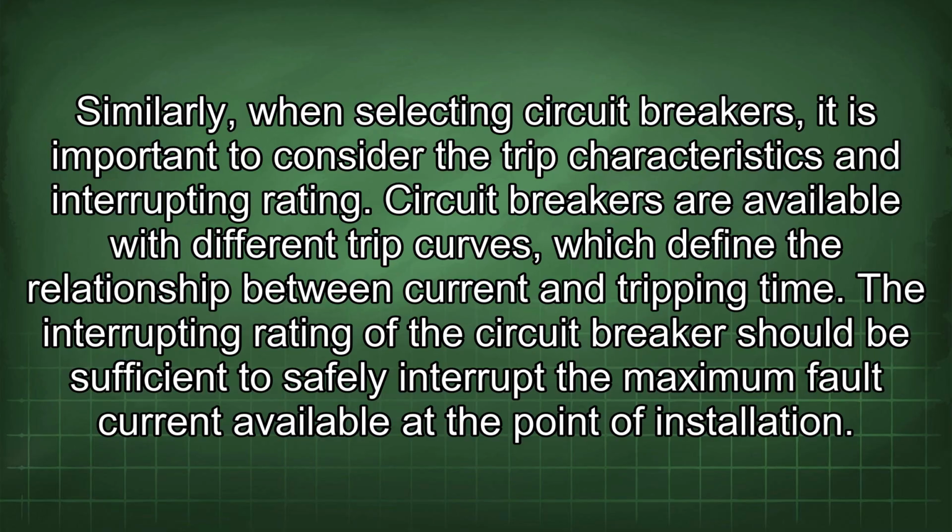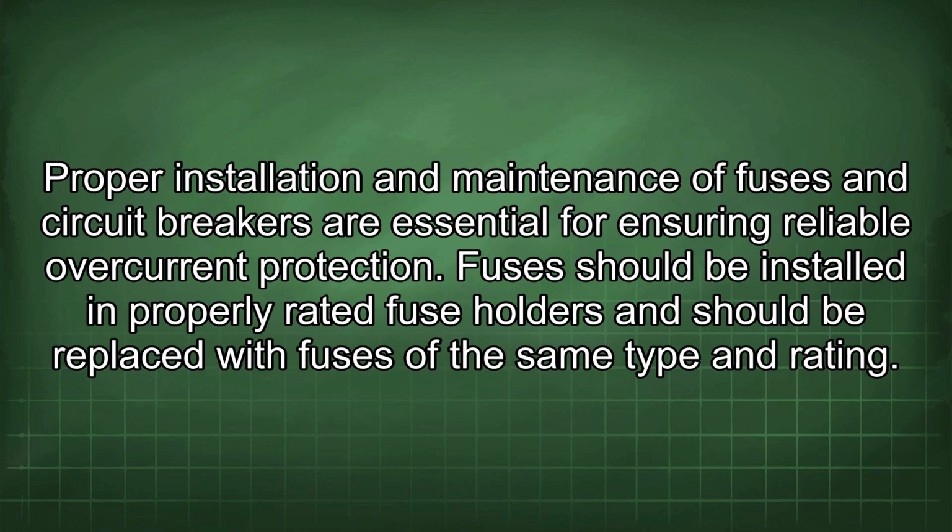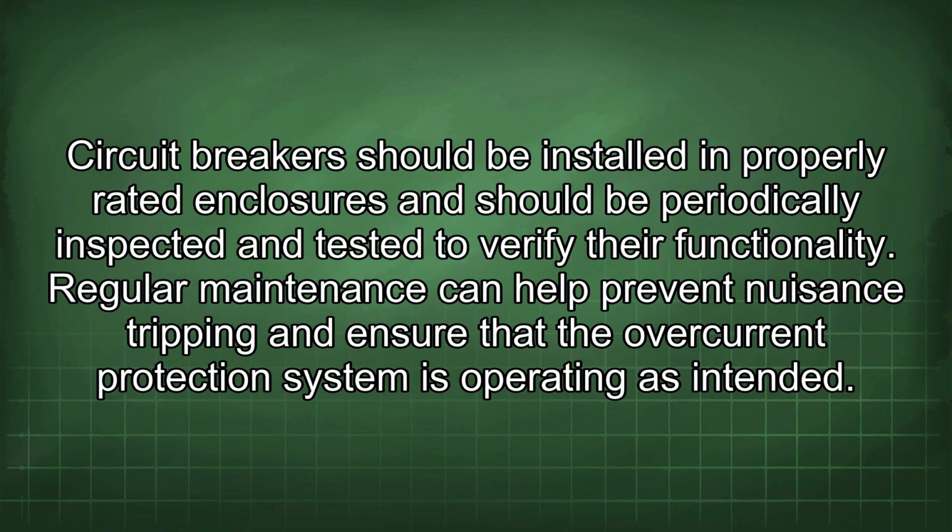point of installation. Proper installation and maintenance of fuses and circuit breakers are essential for ensuring reliable overcurrent protection. Fuses should be installed in properly rated fuse holders and should be replaced with fuses of the same type and rating. Circuit breakers should be installed in properly rated enclosures and should be periodically inspected and tested to verify their functionality. Regular maintenance can help prevent nuisance tripping and ensure that the overcurrent protection system is operating as intended.